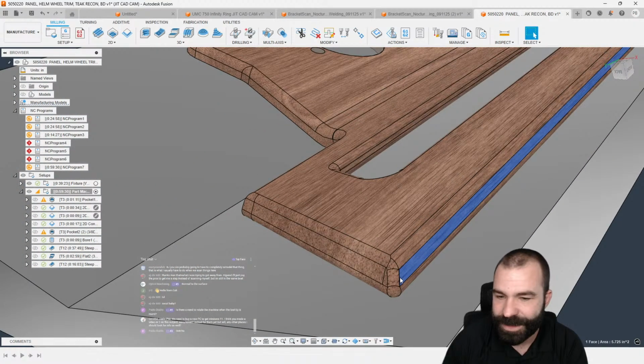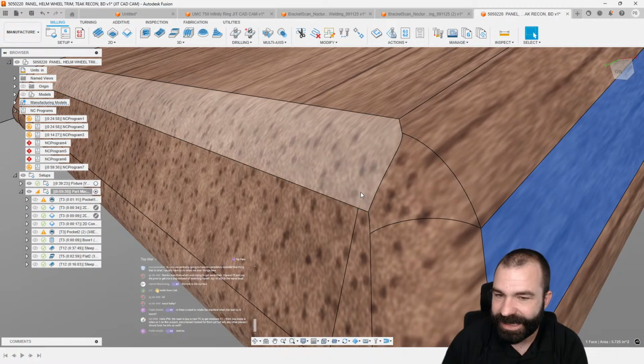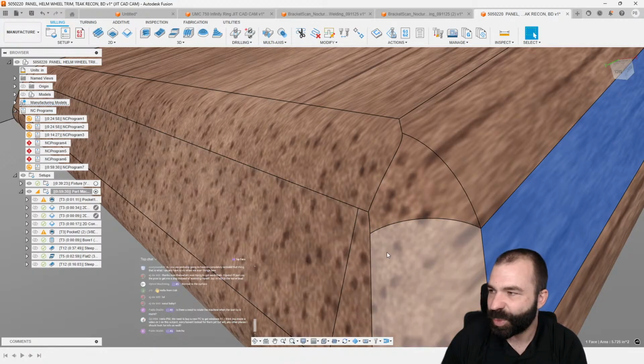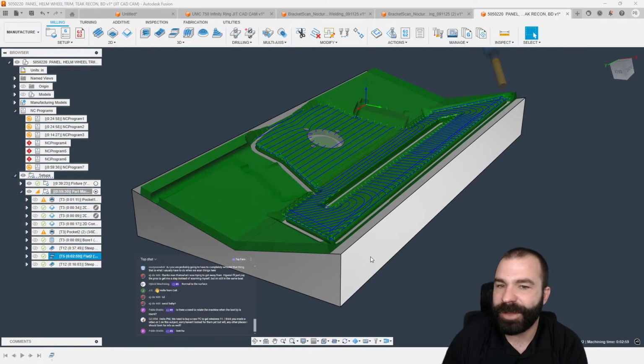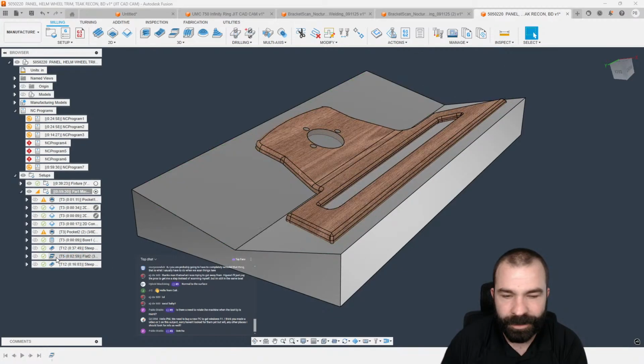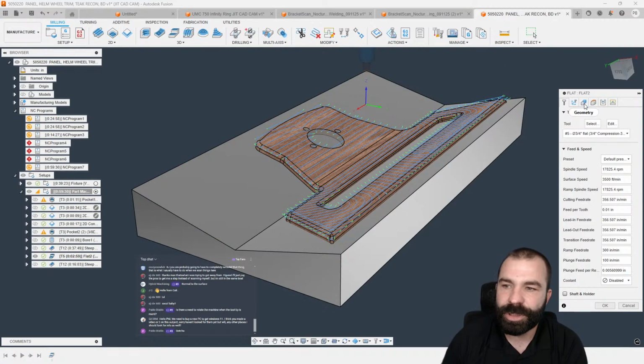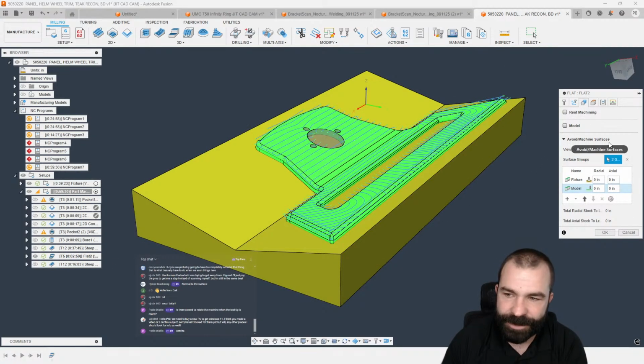I think what I would do is, this is not the cleanest of beveled edges here, so swarfing this isn't ideal. But again, something like a flat strategy has worked out quite well in this particular part. You could, of course, go back and change your geometry out.